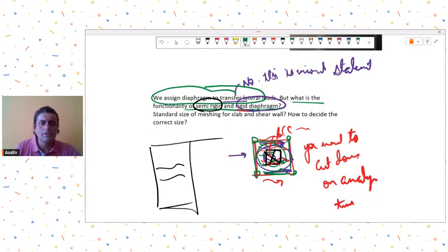This problem of semi-rigid and rigid comes generally where you have wooden floorings or where you have steel decks. Generally, if you see in Western countries, in America, Canada, Europe, etc., many of their floor constructions happen in timber. So over there, it's a problem that your floor panels are not rigid enough.